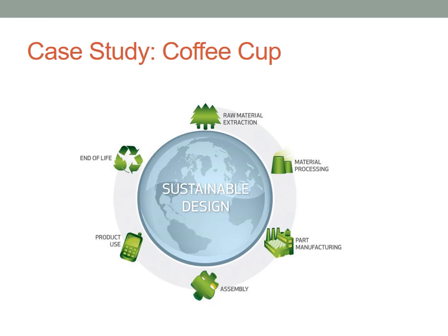And later on, you're going to complete a workshop that will allow you to use a very simple plugin in SolidWorks to allow you to get data based on, okay, if I choose one material for this part, or if I swapped it to another, how much environmental impact could be reduced or lessened. If I manufacture it in Asia as opposed to Europe, where it's going to be sold, and any finishing treatments we're going to put in it as well.